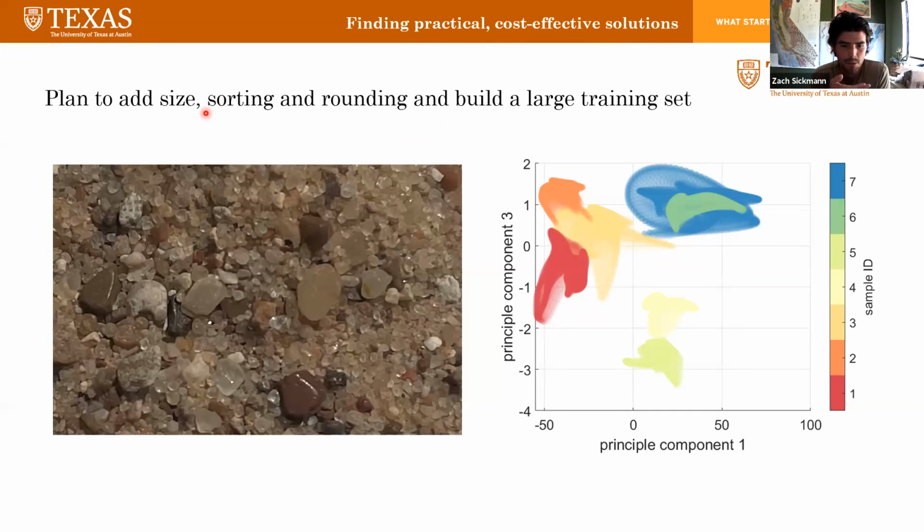So this method wouldn't really work for a weathered sandstone, or for a grungy, chemically altered or diagenetically altered set of sand. But the sand that goes into concrete is very clean, very fresh river sand that is washed. And so the spectrum of colors produced by the individual grains in these samples is more consistently representative of the mineralogy of the source regions, or at least that's our working hypothesis here. And again, the initial efforts suggest that it's going to work, or at least it's going to work